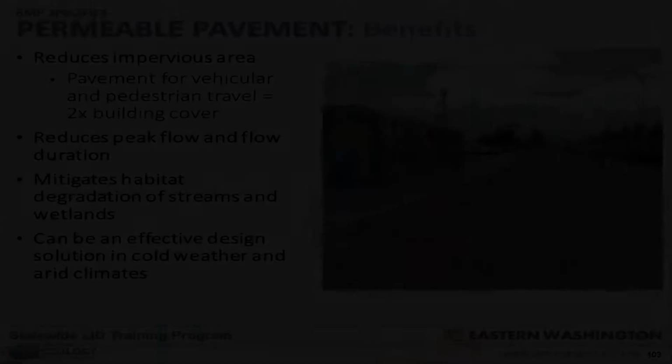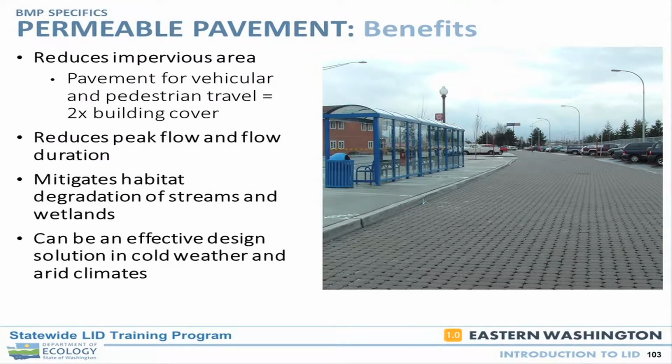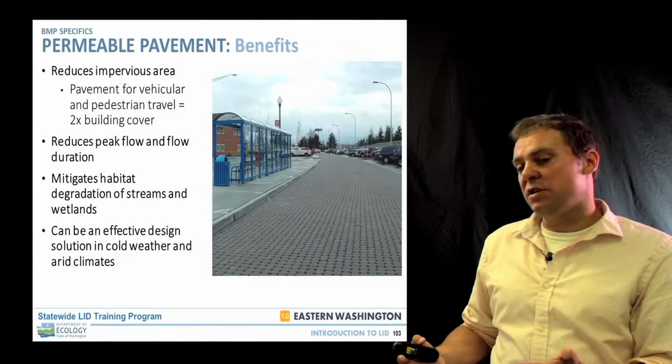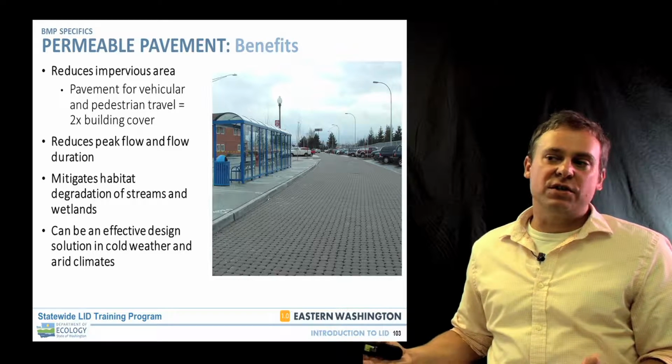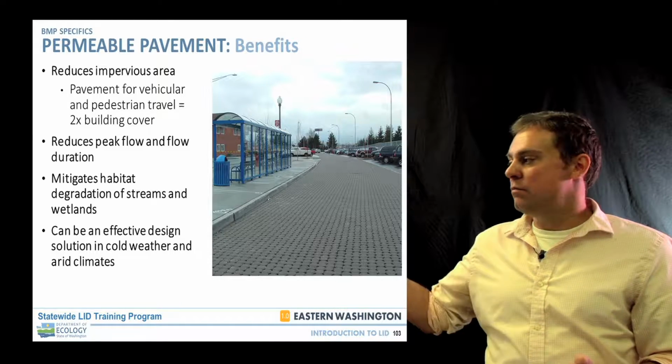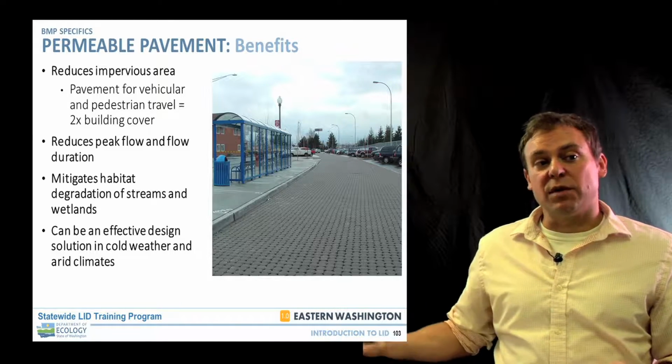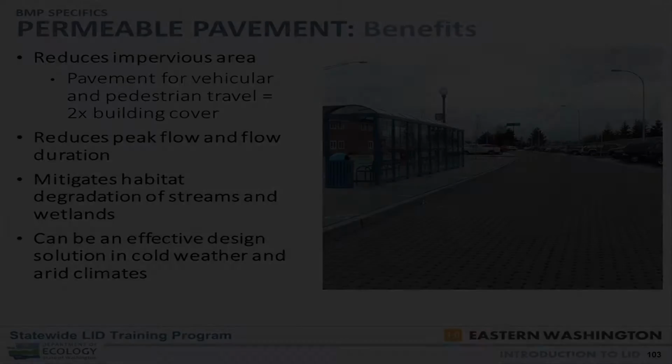Benefits of it: it reduces your impervious area. If you have a porous surface, then it's not something you need to manage anymore. And that's why I like this practice so much, because it doesn't take any additional footprint. It may be a little bit higher cost initially, but you're not building any additional infrastructure to convey the runoff, to retain the runoff, and treat the runoff. It's all done right there at the site.